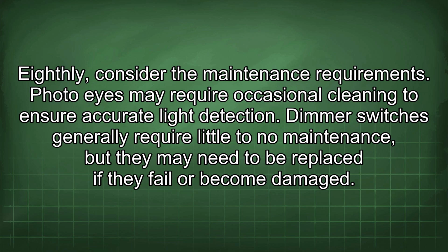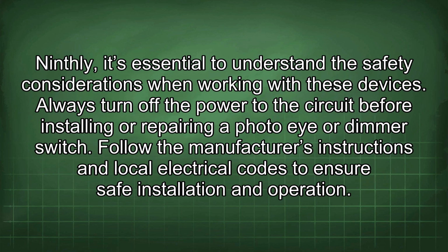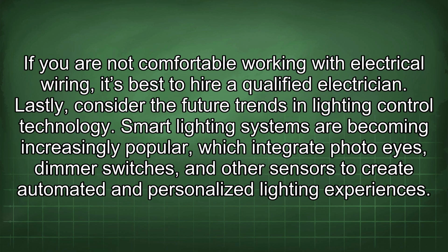Dimmer switches generally require little to no maintenance, but they may need to be replaced if they fail or become damaged. Ninthly, it's essential to understand the safety considerations when working with these devices. Always turn off the power to the circuit before installing or repairing a photo eye or dimmer switch. Follow the manufacturer's instructions and local electrical codes to ensure safe installation and operation. If you are not comfortable working with electrical wiring, it's best to hire a qualified electrician.